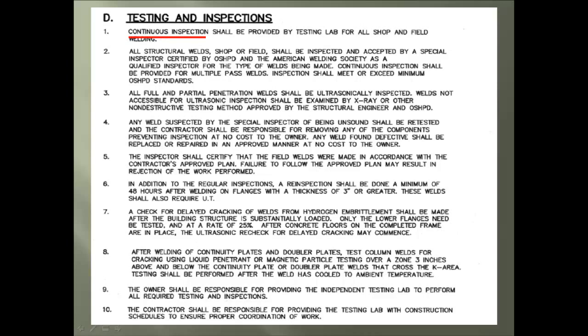Shop and field welding shall have continuous inspection. Special inspection shall be approved by OSHPD. Field welds shall be made in accordance with the approved contractor's plan. Notice the 48-hour rechecks of welds on flanges 3 inches and thicker.